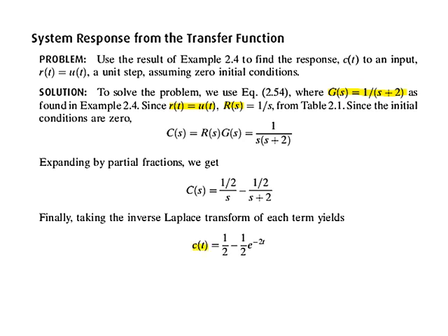For this, as we know that step input is represented by 1 over s in Laplace domain, and the output of the system is equal to input R of s multiplied by G of s in Laplace domain. Now for time response, we will check whether the relation of C of s looks familiar from any relation in the Laplace theorem table or Laplace input signal transform table.